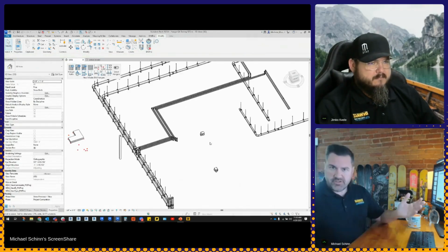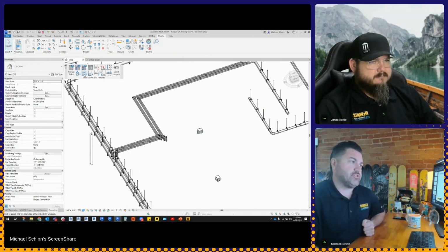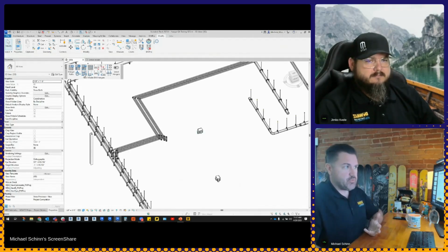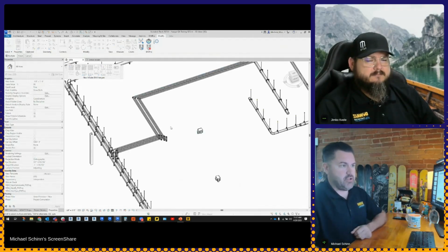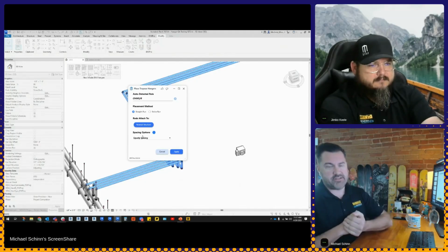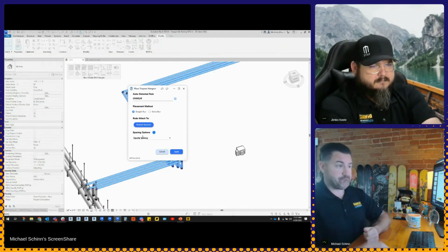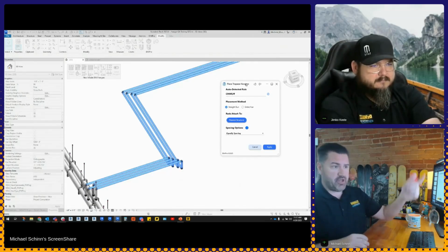So you can see the concept here with your single rod hangers. Next, let's dive into the trapeze hangers. Well, I want to be able to place some trapeze along this run here. Let's just grab those in this scenario here. I'll click finish. Again, it recognizes all the systems that are part of that group. So this is my chilled water supply, heating hot water return run as an example.